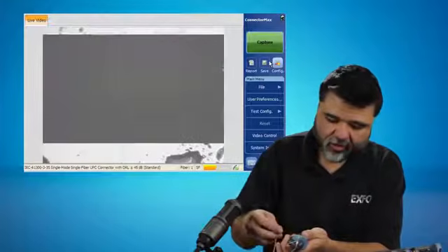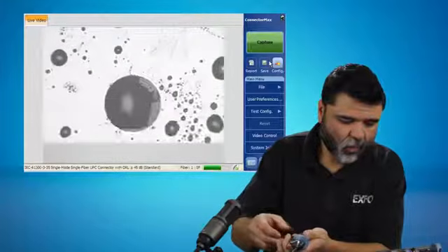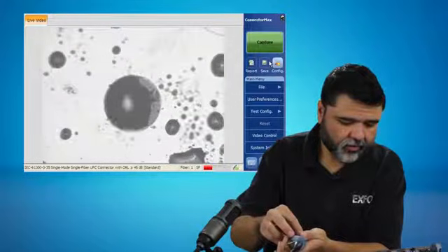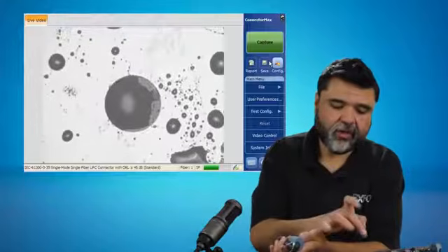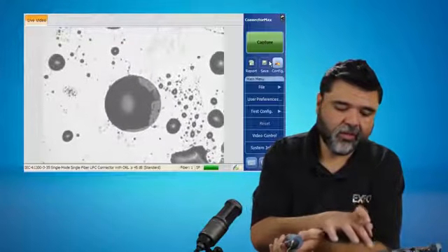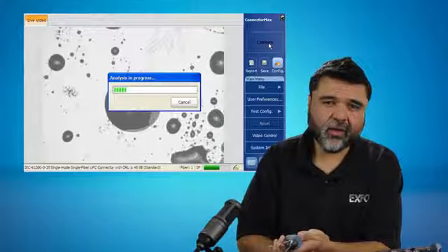And so we have quite a bit of oils and whatnot on the end of this fiber. So, if I were to do a pass-fail on this fiber right now, it would clearly fail. So I'm going to go ahead and do a pass-fail capture on this one. So I'll go ahead and run connector max.